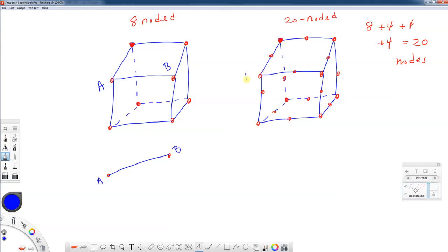When this deforms, let's call that A and B, we have 3 nodes, so we have the ability to fit a cubic through there. Instead of just a first order line, we can fit kind of a cubic. So the way that it can deform along that edge is a little more sophisticated. You also have the ability to capture initial curvature easier as well.